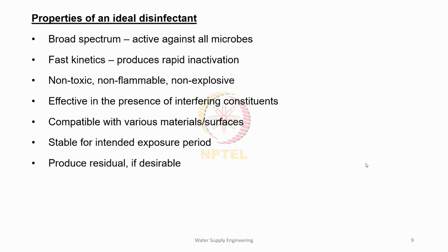And another important parameter is, if desirable, it should be able to produce a residual. After all the microorganisms present in the water sample are removed, some amount of disinfectant should remain, to protect from any possible future contamination. If that happens, this residual can act and again disinfect the water sample. And another thing is, it should be easy to generate and apply, so that it becomes economical.